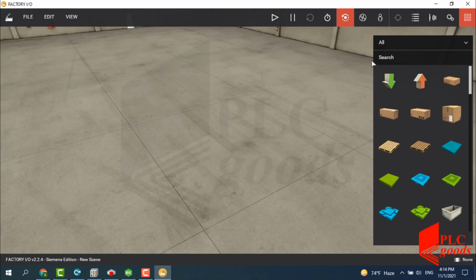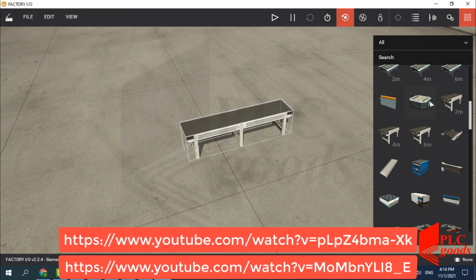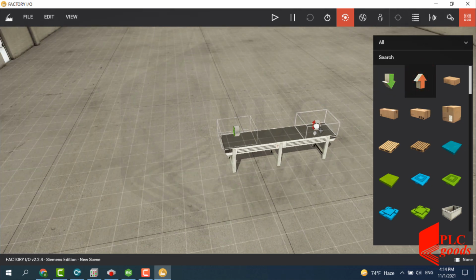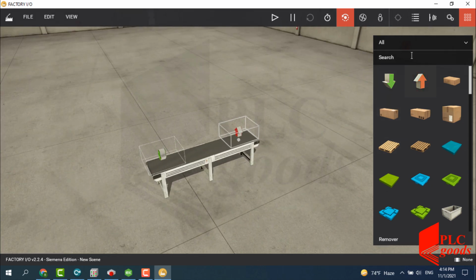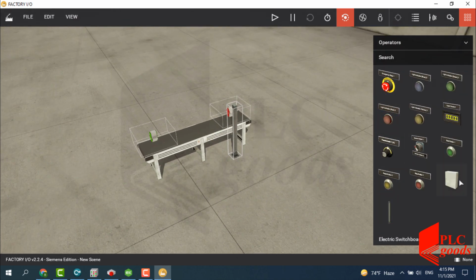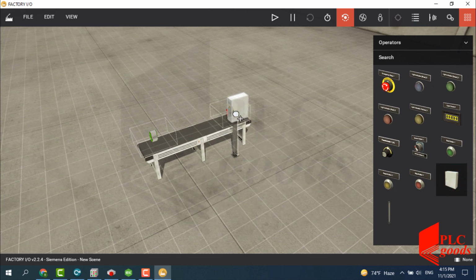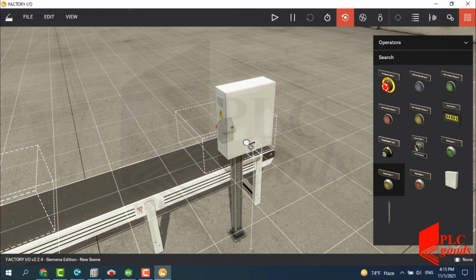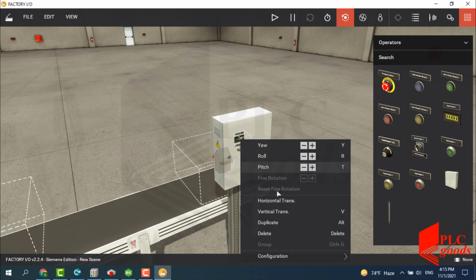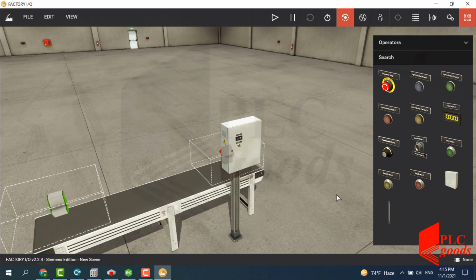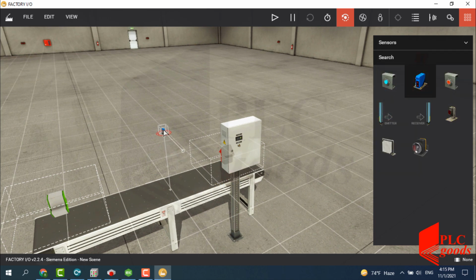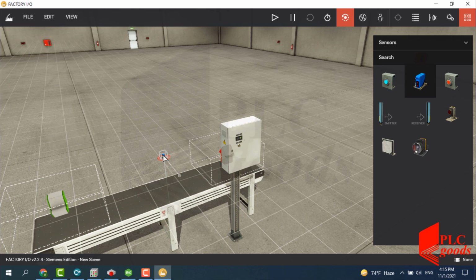Alright, during different videos on our YouTube channel, Factory I/O software was explained and tested. Again, let me design a simple process. Let me select the integer mode for the inserted digital display, because I want to display the counter value. Now, let me use a sensor to detect boxes. It will be used to enable the counter inside my program.